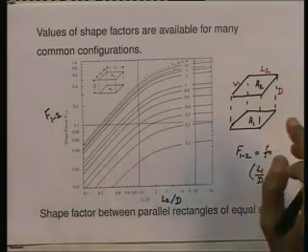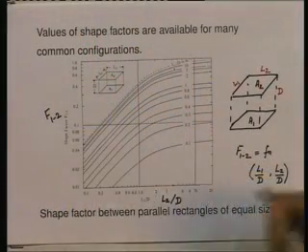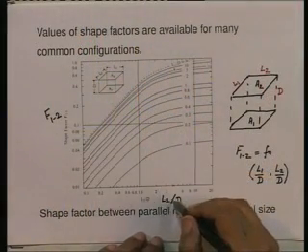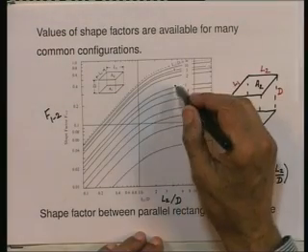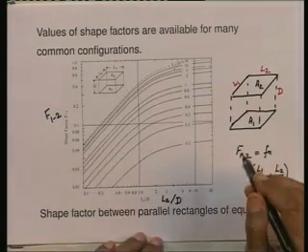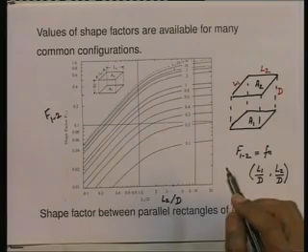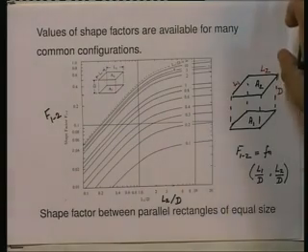So, for a given situation in practice, calculate L1 by d, calculate L2 by d, go to this graph with L2 by d, go to the appropriate curve for L1 by d, and read off the value of f1 to 2. That is what you will have to do.